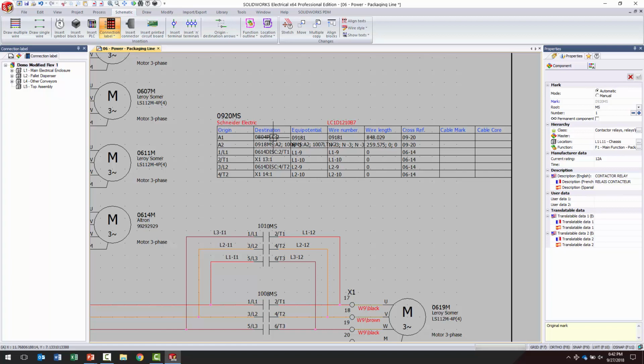When we make a print packet, we make 2 versions. We make the customer version and we make our production version. The customer gets a parts breakdown with our part numbers on, so they order from us. They get an electrical power distribution schematic. They don't get every wire and all that. Just the huge power goes to our panels. The production gets print detailed enough to build the panel to wire.